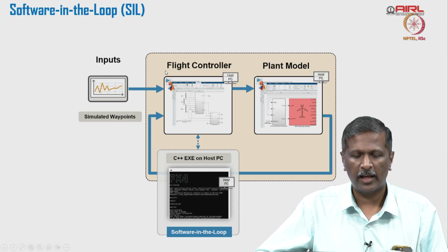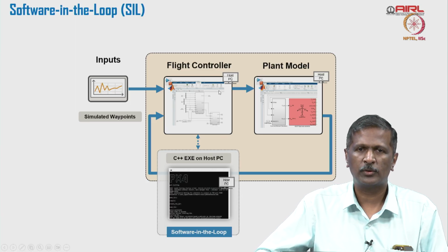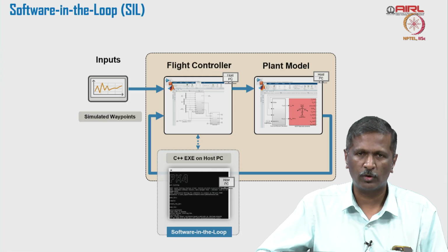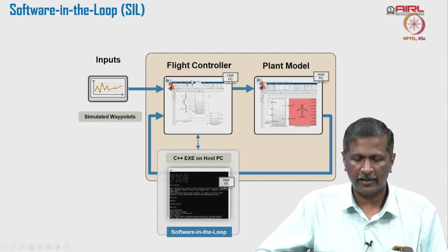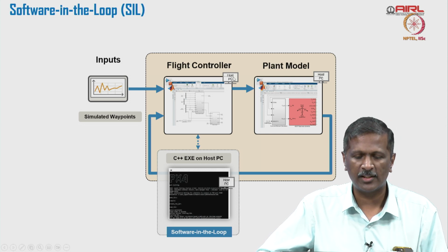Once that's put into the simulator, your flight controller comes into the picture. The flight controller looks at the flight management module, which will see where to do takeoff and then go from point to point navigation, which we will be covering later, and then how control is going to execute, whether you want to fly in attitude mode or in velocity mode, velocity tracking or position tracking.